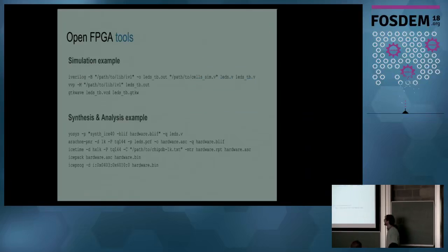You can use these tools by typing these commands. For example, in the simulation, you can run iverilog, then vvp to generate the simulation file, and then GTKWave to visualize all the lines. And for synthesis, you can execute Yosys, then Arachne-pnr, icepack, and finally iceprog to program. You need to type all that.